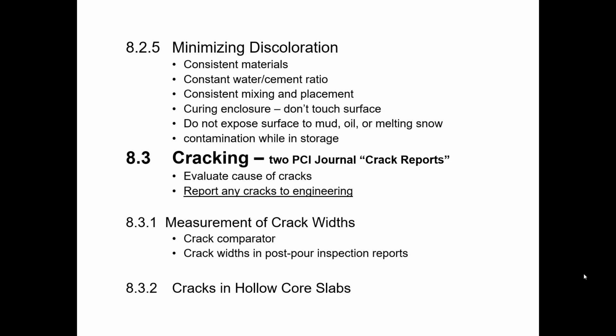But it's basically, once you notice this efflorescence on a piece, it's going to be something that you, in many cases, are going to want to try to remove. And the methods to try to remove it, you could probably guess at what some of those are. The first step might be we'll just use a stiff, bristled brush to try to scrub it off.